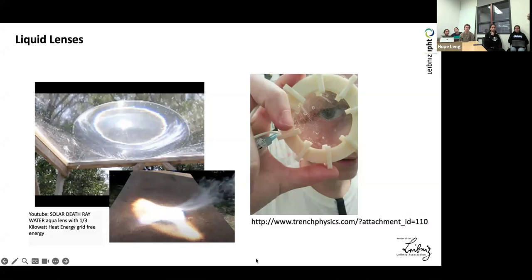And then when you throw many stones in this grinding plate, they all average out to a single size. So there is a batch effect, but they naturally average out because if there is a big stone that's taking more weight than the small one, it'll wear out faster. So again, another principle of exploiting what happens naturally as a way of building an optical component.